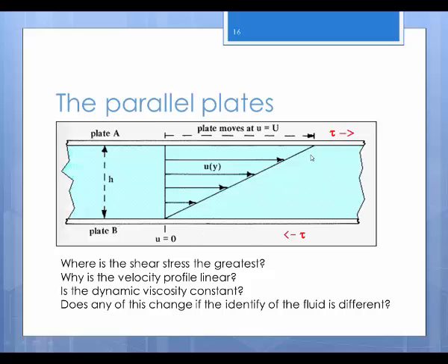So the last thing is there's something in the book that discusses a no-slip condition. So what is a no-slip condition? Why is it important? No slip means that at a solid boundary, if, for example, down here, this plate is stationary, it's not moving, the no-slip condition says that the fluid that's right next to this plate has zero velocity. So if you go all the way down here, this velocity says u equals 0. It means the plate is 0, and the velocity of the fluid actually does go to 0. This fluid at the bottom does not move.